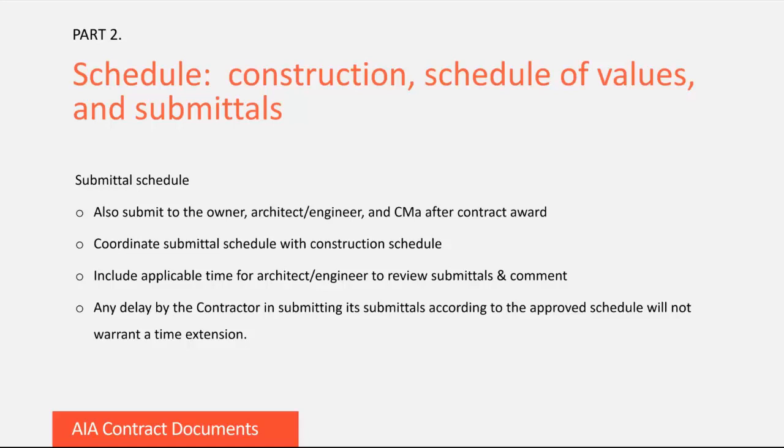After the architect, engineer, CMA review the schedule, they will inform the contractor of any submittals missing from the list. Sometimes they will ask the contractor to provide submittals that are not called for in the specs. Generally, things like a copy of the contractor's safety plan, certification of crane assembly, certification of the crane operator, and records that employees have undergone safety training, especially in road and traffic safety.